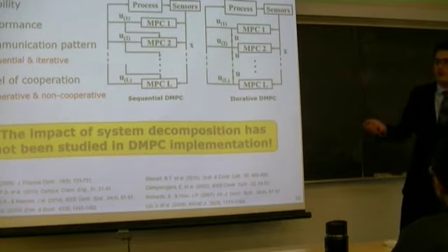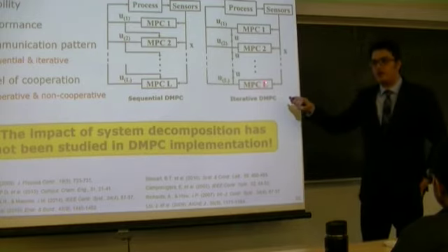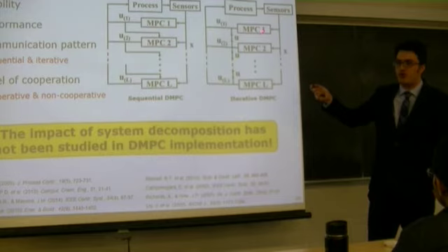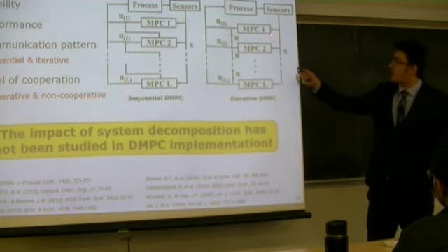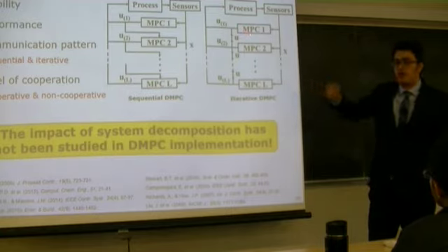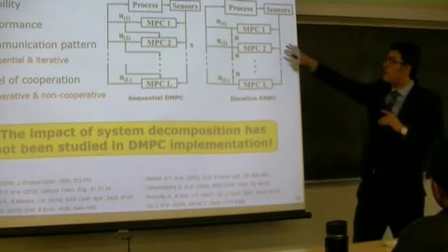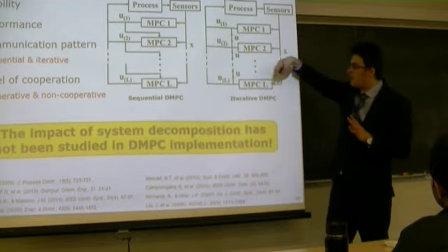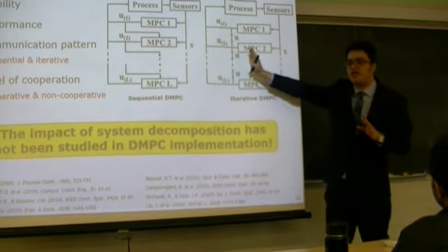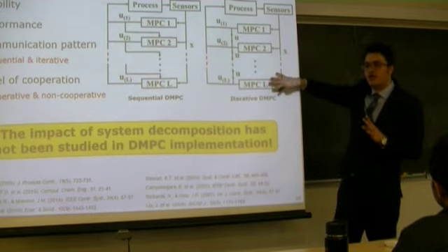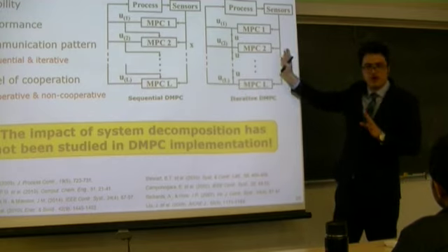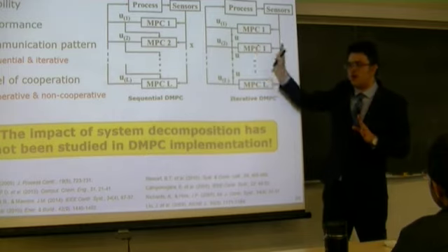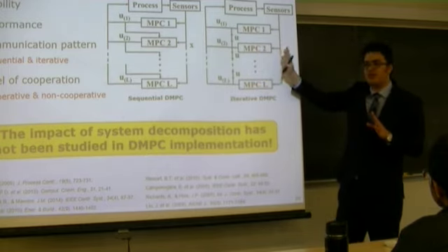Here. So in the iterative controller, the MPC, each of the local controllers solves their own local dynamic optimization problem and computes the manipulated inputs. After the first round of simulation, the computation time is equal to that of the controller that takes longer, since all of those optimizations are handled in parallel.